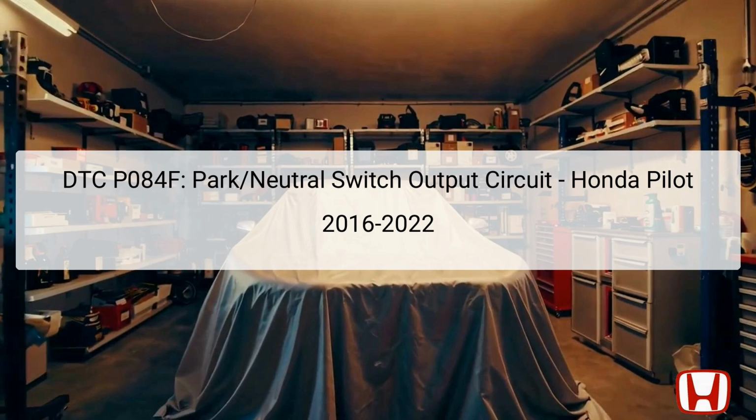It's important to note that this DTC is not a consequence of mechanical issues within the transmission, but is strictly an electrical fault. The correct functioning of the park neutral switch is vital for the vehicle's response during shifting and ignition. If this error code appears, troubleshooting is necessary to pinpoint the electrical issue at hand.